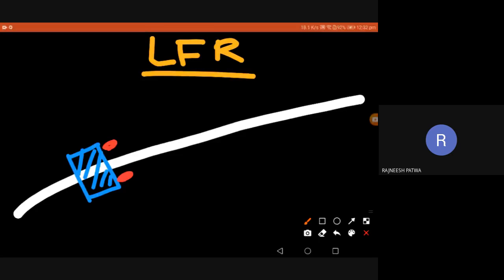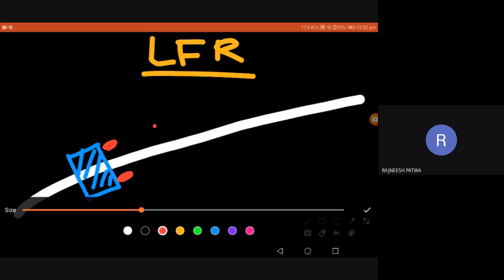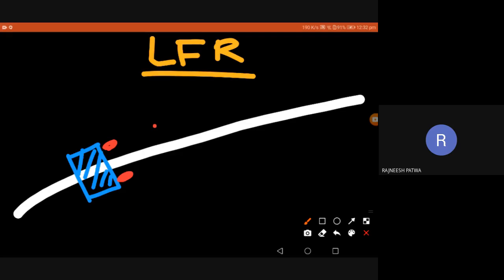So this kind of sensor, I call one kind of sensor. I'll tell you about the IR sensor. It consists of an IR transmitter and an IR receiver. For example, this is a transmitter. I have an IR transmitter, which I represent using a simple LED. When this LED is powered, when given some power, we call it V or voltage, it is sending its transmission. It transmits some radiation, we can say IR radiation.